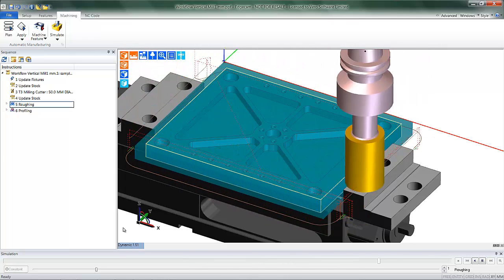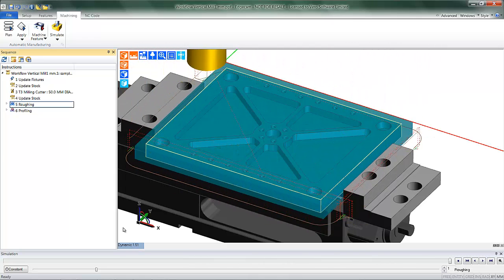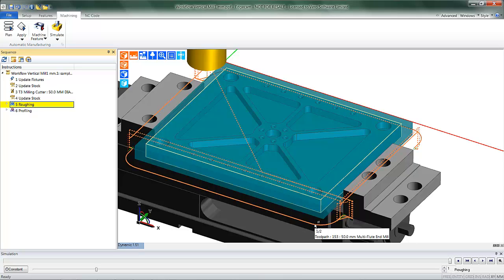So this time we're cleaning up material all the way down the X-axis while stepping over the material that we see in the Y, and this is due to the new clamping positions on the vice. So that's the new fixture avoidance command inside Edgecam Workflow.